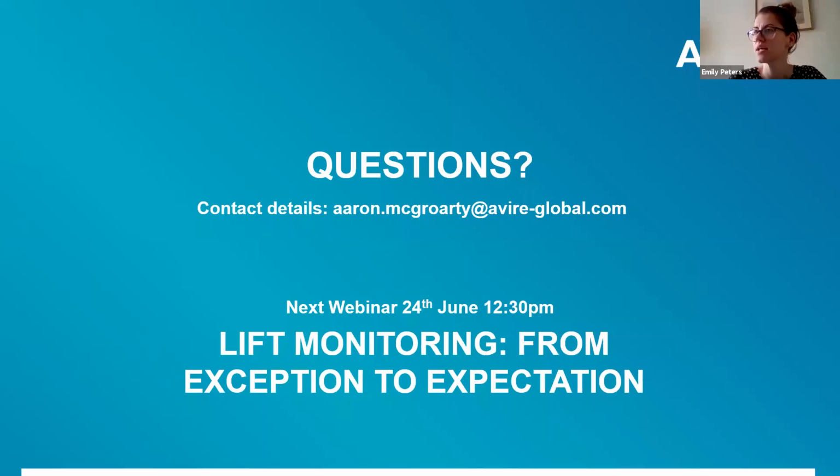Perfect. Right. A question here: is the type of mirror glass for the mirror displays regulated? Here they've put as part of, I don't know if that's the EN81-70 or if that's a typo. I'm not sure. No, I don't think it is regulated. I think the vandal-proof regulation is actually in a different regulation, isn't it? EN81-80 or something. I would have to double check. But when I was reading through the EN81-70 regulation, there was no reference to vandal proof in the mirror glass.